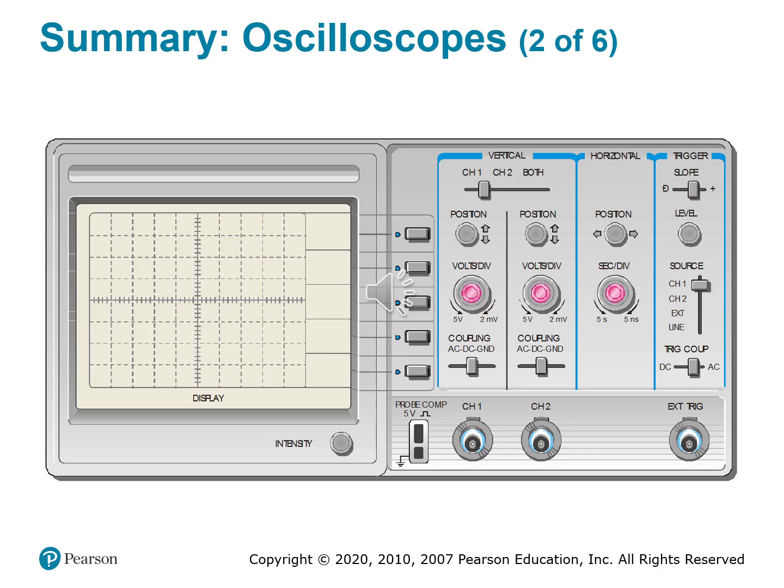So trigger section to the far right, that trigger area stabilizes the waveform. So key controls like the slope, positive or negative, determines if the waveform starts on a rising or falling edge.